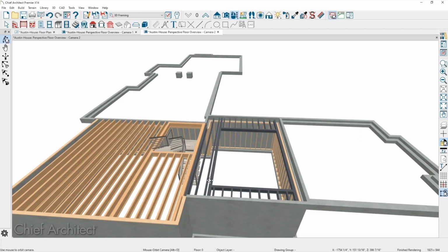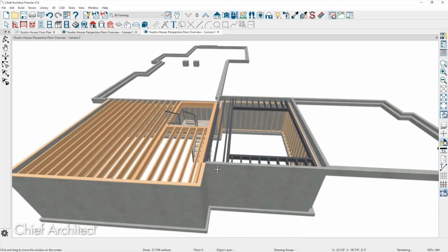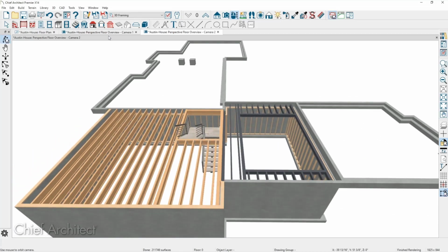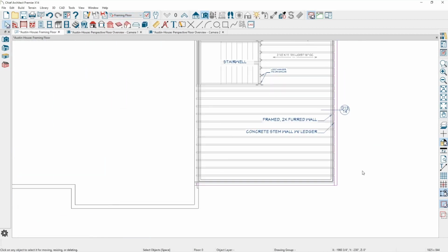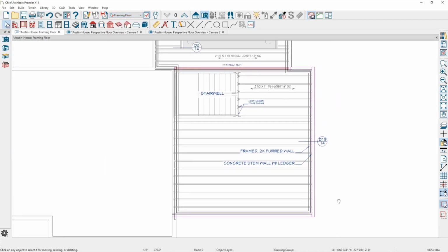Okay, so how would you add just extra beams and piers throughout the entire structure, more of a checkerboard pattern? Yeah, so when you have the design, I'm going to do floor framing here in a few weeks. But if I switch this view over to the floor framing view that we were just looking at, and let's just assume that I'm going to throw another beam in here, then I come up underneath the tool for the floor framing, and there is an option over here for a floor and ceiling beam. See that? Okay.